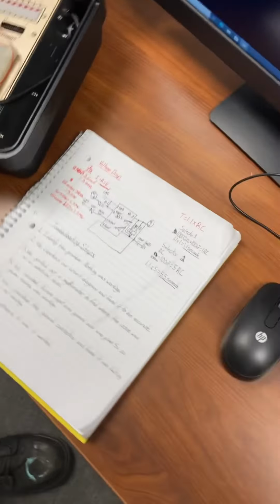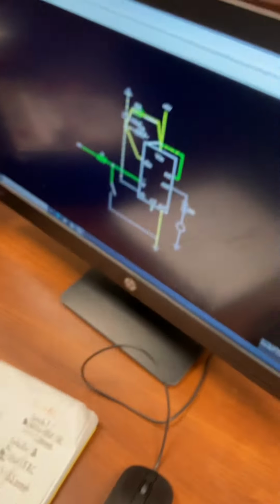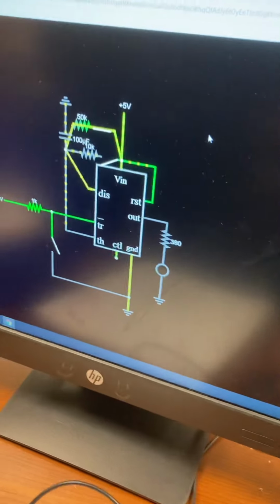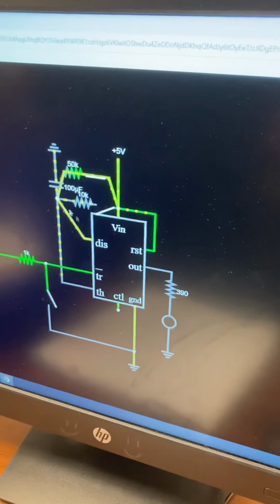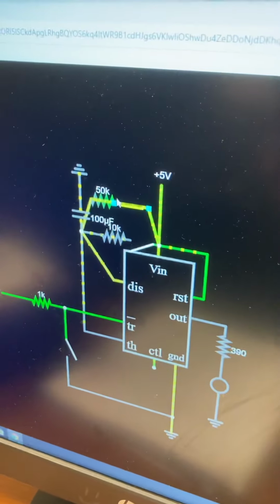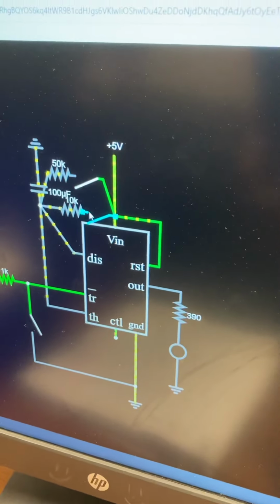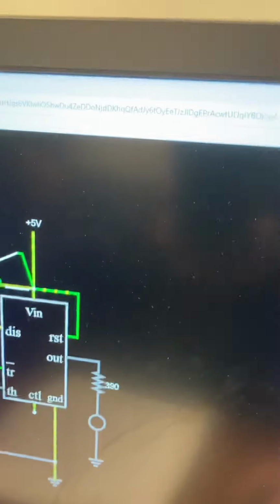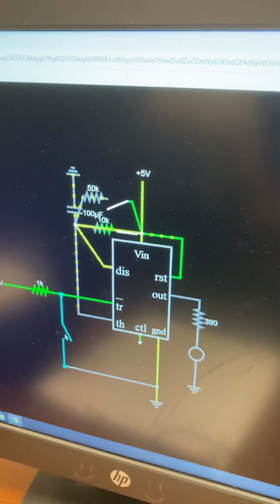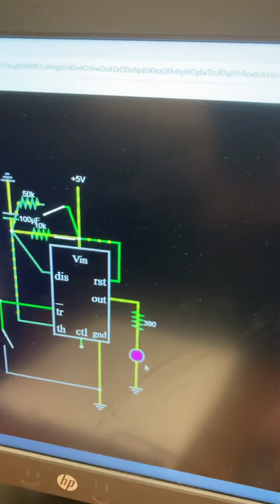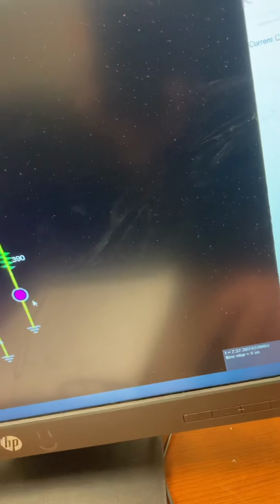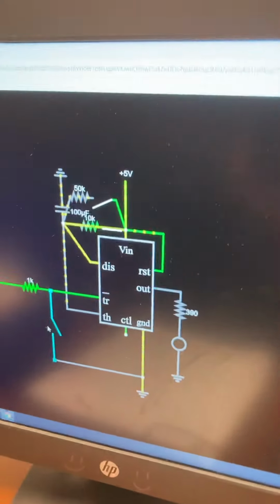And that about sums it up. We actually also have our Falstad diagram here that we built. You can see we got the 10K and the 50K resistor on switches. So if we take the 10K and close it at switch 1, and we press the button here, then you'll see the light switch takes about 1 second. The timing on here is a little less than actual seconds. It's about half a second, so it takes twice as long real time.